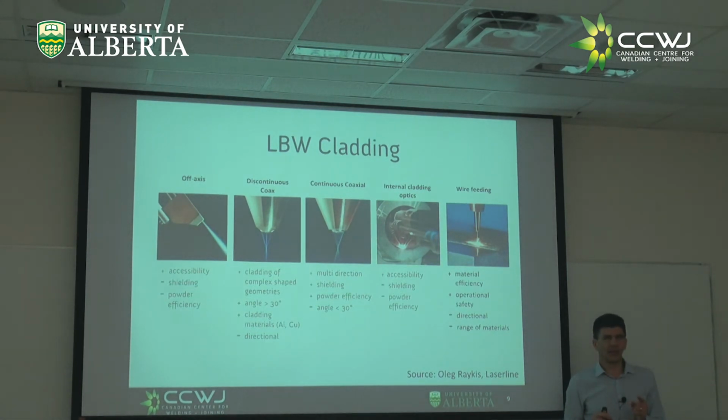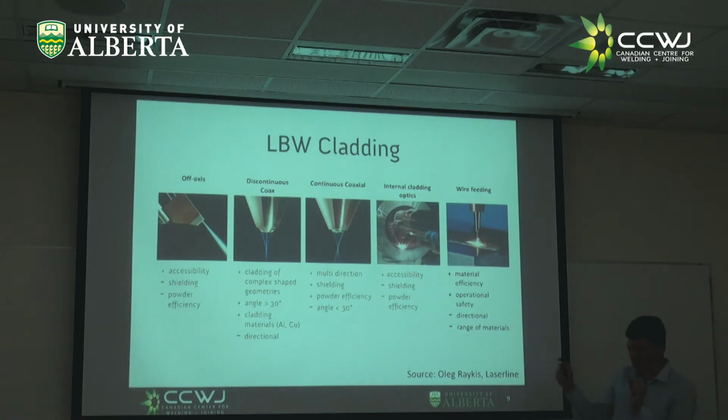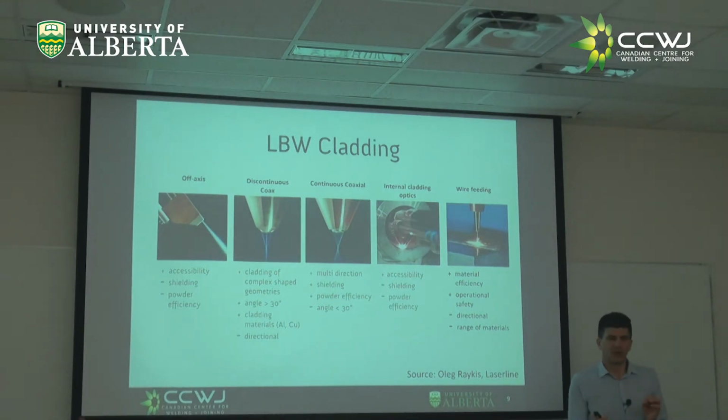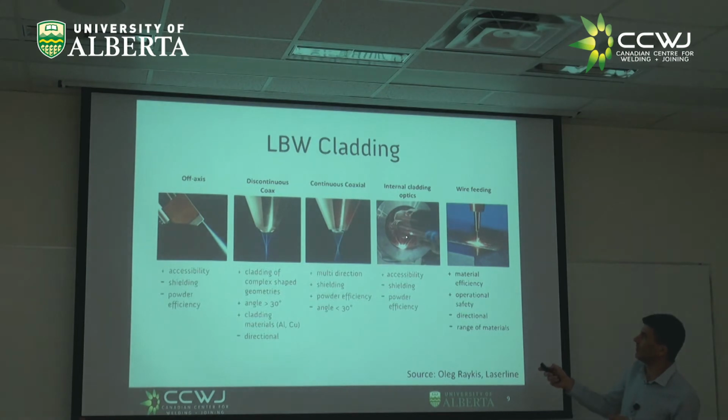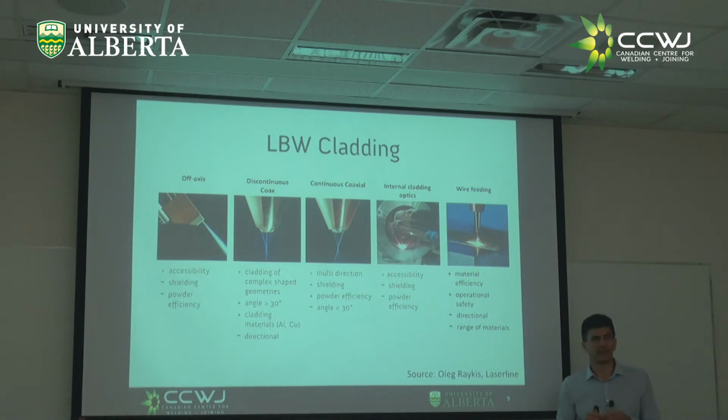And then you're putting many kilowatts in, so you often have a mirror here. Sometimes you bend the fiber, sometimes you have a mirror, but you need some sort of optics. If any powder goes back onto your optics, it absorbs a lot of this thermal energy and fuses to the optics. Now the optics is ruined and it starts to absorb more energy. So it's a little bit of global warming of laser heads, right? So one of the highest challenges of internal cladding is keeping the optics clean, right?